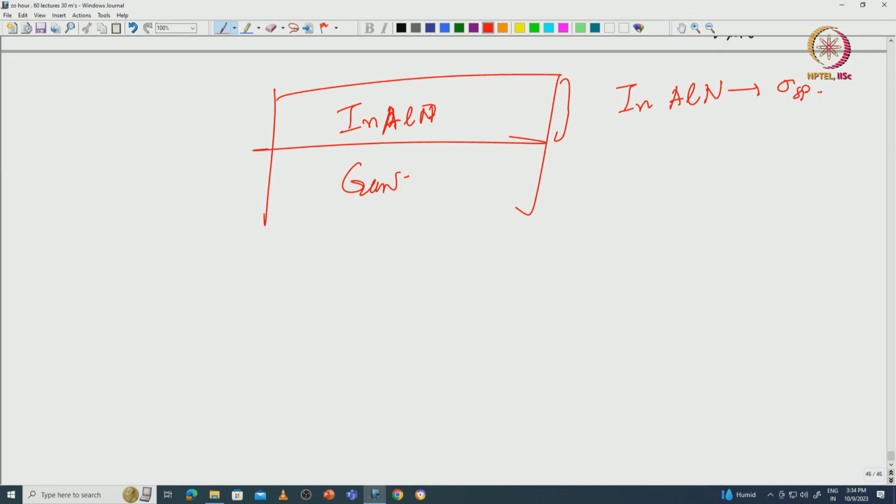If you put indium around 17% and aluminum around 83%, you can calculate the polarization or the lattice mismatch at different compositions of indium and aluminum. Of course, it's just plain math. People found out that with 17% indium and 83% aluminum, the lattice constant a of indium aluminum nitride is exactly equal to the lattice constant of GaN,